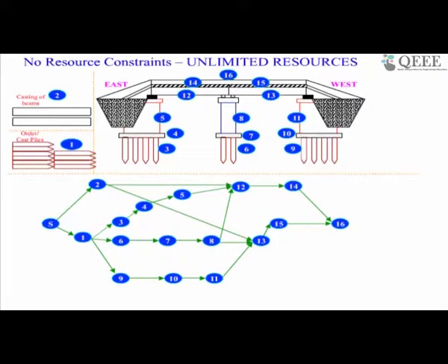Okay, to place the girder here, obviously the girder has to be ready. After the girder is ready, both this pier and the abutment have to be in place for the girder to be placed. So you can see that for the girder to be placed, my predecessors are: girder is ready, east abutment is constructed, and the pier is constructed. Only then the girder. So this is a physical predecessor relation.